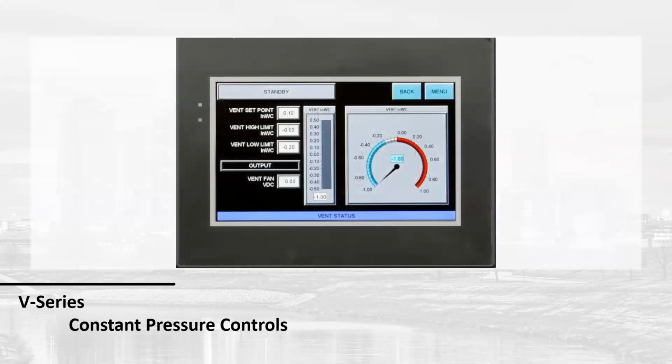There's just a quick screenshot of our 300 series controllers. Everything that you need while you're tuning the boiler is on that screen. So it's really simple for commissioning. Just come in here, set your high limit, your low limit, your set point. The nice thing is that this is all happening in real time, so you can see how those changes are affected in the system.